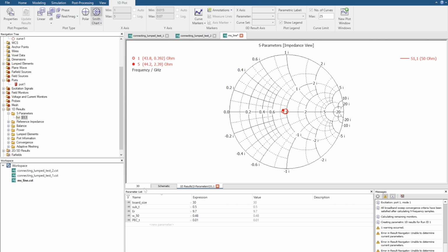Okay, so these are the results of a 50 ohm line. Now, what happens if we change this to 100 ohms? We should know from learnings about the Smith chart that we should see the same circle here, but expanded all the way out from this point at 0.5 and then all the way out to 2. We should see quite a large circle. So let's have a go testing that.